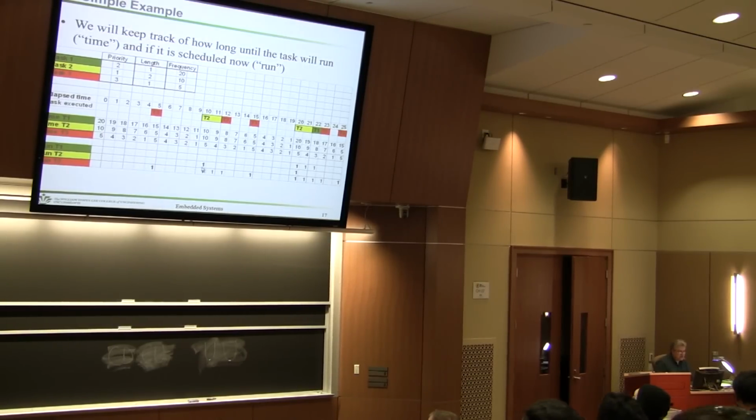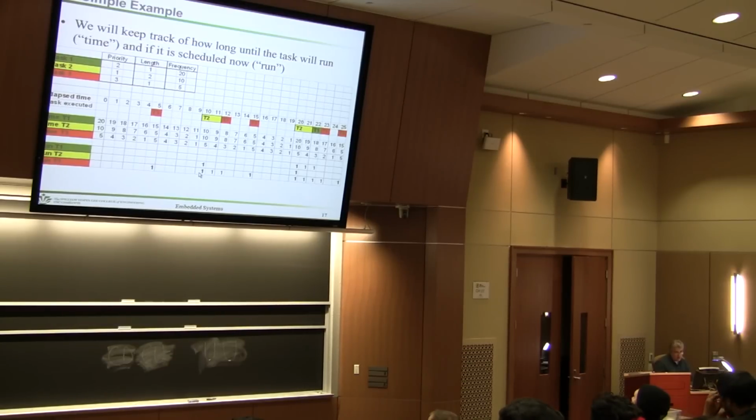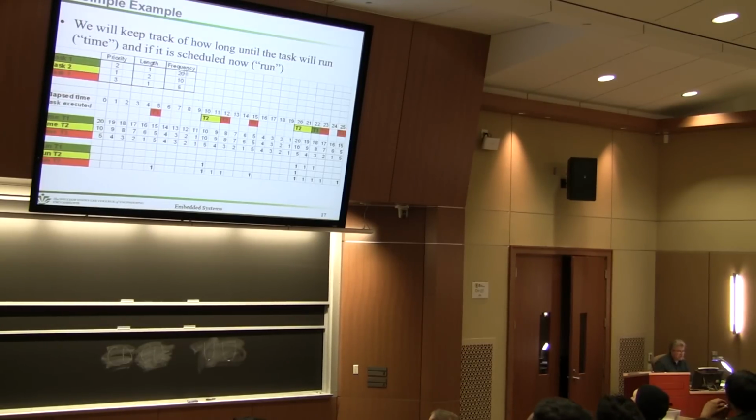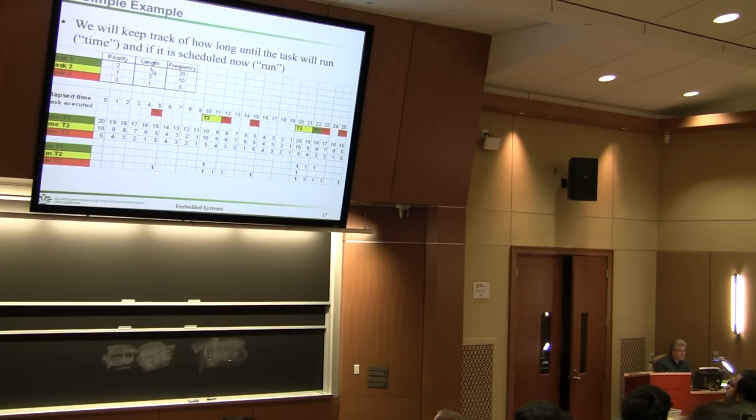So in this case, we're going to identify that task 2 and 3 can start at the same time, but of course only one can run at a time. So we take the one that has the highest priority. This says priority 1, so task 2 would run first. This is the amount of time it takes. If each timer tick is, let's say, 1 millisecond, what we're saying is that the tasks are going to take 1 millisecond, 2 milliseconds, and 1 millisecond.